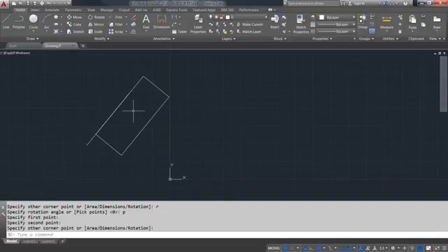Right. When you bring a drawing element in from another drawing, it will take your current insertion scale into effect, and it will scale the foreign object, if you will, that you're bringing in. It will scale it in a way that it matches up with the insertion scale set in your current drawing. It doesn't change a setting in your current drawing.